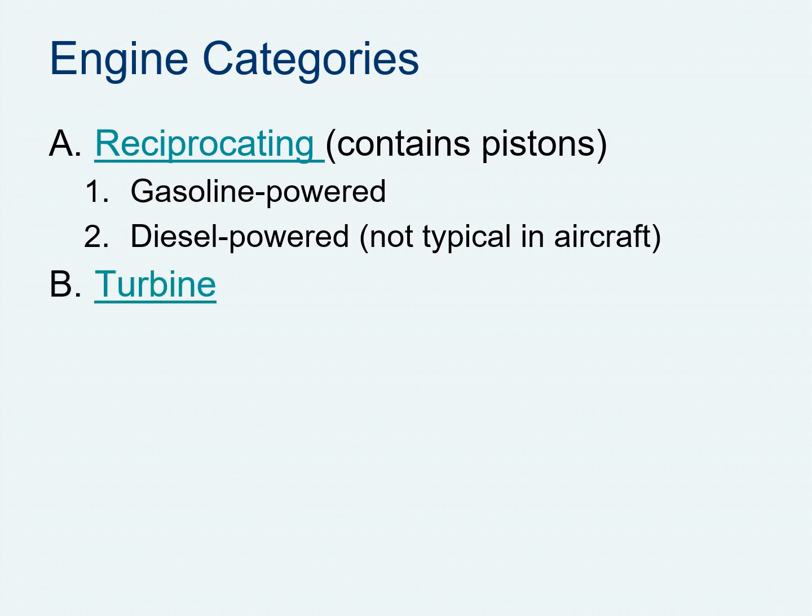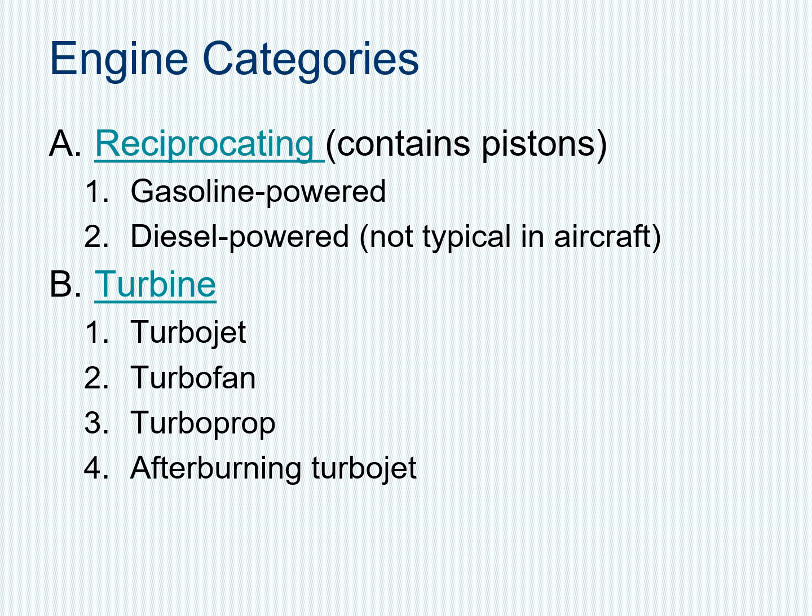The basic classifications are turbojet, turbofan, turboprop, and afterburning turbojet. Other than this, we have a turboshaft engine that we are using in helicopters. Turbojet we are using in fighter and bomber aircraft. Turbofan we are preferring for passenger aircraft, and turboprop we are preferring for passenger as well as cargo aircraft. Afterburning turbojet, we are especially preferring for very high speed aircraft. Those are fighter aircraft.